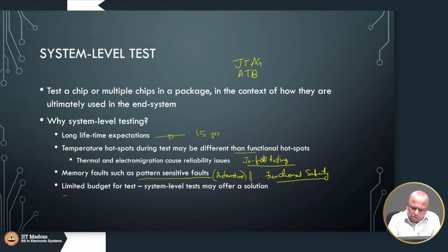When the budget is a concern, if you have a very expensive tester to apply your scan tests and so on, then it's fine. But it may be possible for you to apply system level tests and reduce the amount of testing you do with the tester. So it can act as a potential replacement for external testing.